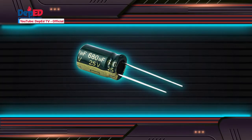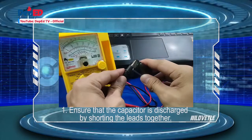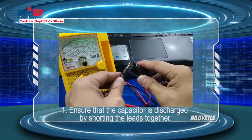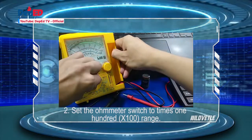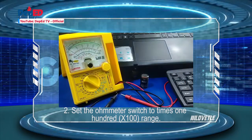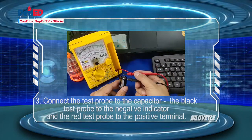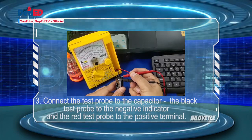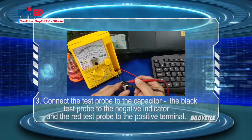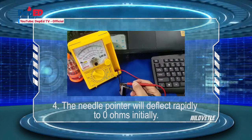Here are the steps in the proper way of checking a capacitor of 600 microfarad using an analog ohmmeter. Step 1. Ensure that the capacitor is discharged by shorting the leads together. Step 2. Set the ohmmeter switch to ×100 range. Step 3. Connect the test probe to the capacitor, the black test probe to the negative terminal, and the red test probe to the positive terminal. The needle pointer will deflect rapidly to 0 ohms initially.